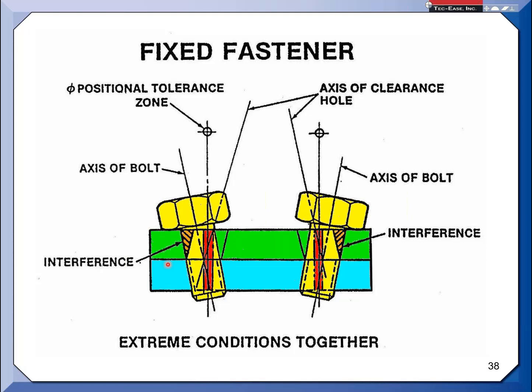So for example, if instead of this real thick part this was a thin sheet metal part, would I worry about projected tolerance zone? Probably not. In other words, the thread engagement is well under the thickness of the plate, so you may not use projected tolerance zone. If instead of this big, thick, 1/2 inch or 5/8 thick flange I had a 1/4 inch bolt and 60 thousandths thick sheet metal, I would probably leave the projected tolerance zone off, because I don't want you to measure that short little distance of what we're controlling. The odds of probability, again, it's like gambling in Vegas, what's the probability of non-compliance? So there you're dealing with producibility. But have I done that on sheet metal parts and not used projected?